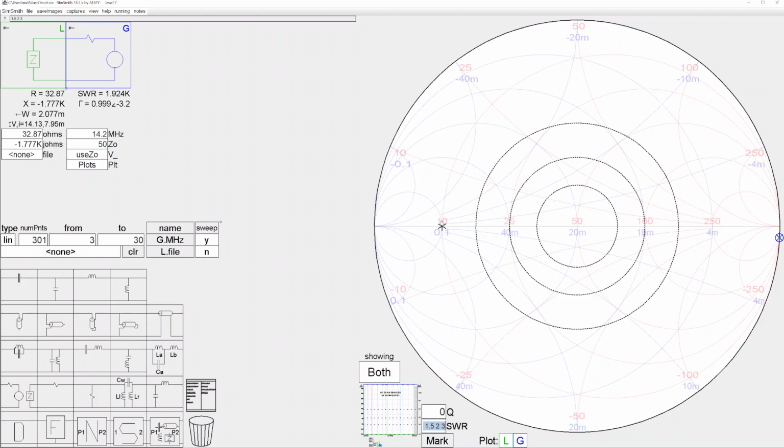One last thing is, if you click anywhere on the Smith chart, you'll notice on the lower right-hand corner it instantly gives us an inspection of that location's Z. Both the SWR and very often the frequency, but right now the Z is 10 and minus 1.36j. If I try to go very close to the equator, it'll be very close to 0j. So that's just an inspection tool with my mouse click.